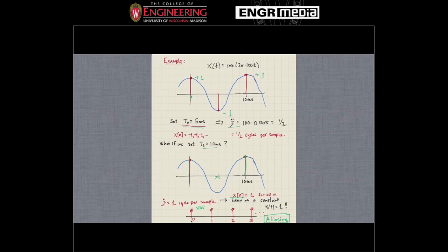And so that's what's called aliasing. So aliasing in signal processing and electrical engineering is just referring to when we take a signal, we sample it, but we don't sample it fast enough. And that results in there being multiple different signals that could represent this same discrete time frequency. So multiple continuous time signals could give us the same discrete time signal. And so that's referred to as aliasing. And we'll spend the rest of this lecture and the next lecture talking about that.